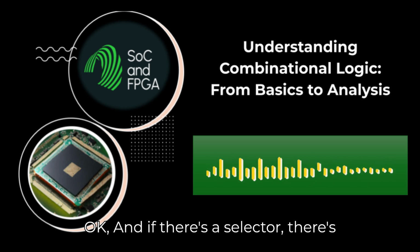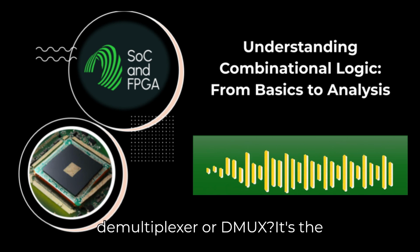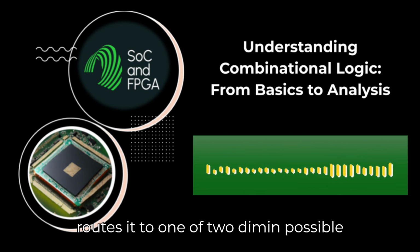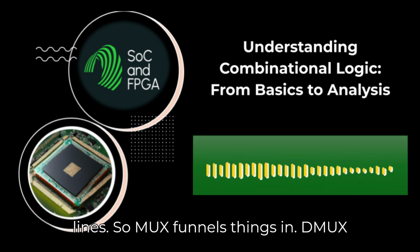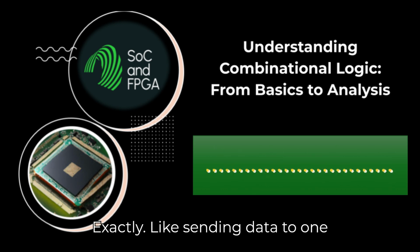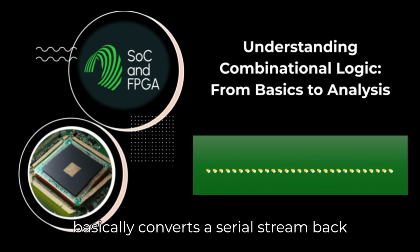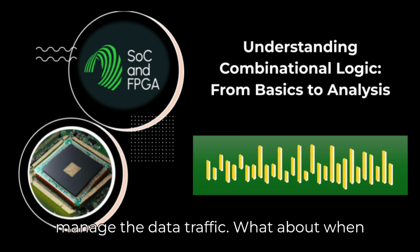Okay. And if there's a selector, there's probably a distributor. You got it. The demultiplexer, or DMUX, it's the inverse. Takes a single input line and routes it to one of 2 to the n possible output lines, again chosen by n select lines. So MUX funnels things in, DMUX sends things out to specific places. Exactly. Like sending data to one specific memory chip or output device, it basically converts a serial stream back into parallel paths. Makes sense. They manage the data traffic.